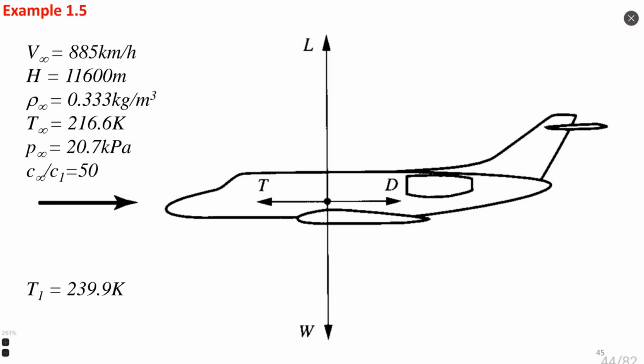One restriction for this particular wind tunnel is that we have fixed temperature of test inside wind tunnel, which can be related to some structural limitations of the wind tunnel. So it's 239.9 Kelvin. I think we can consider as 240 Kelvin. So let's have this example and calculate values of Reynolds number, Mach number, and after define same properties for the flow inside the wind tunnel.